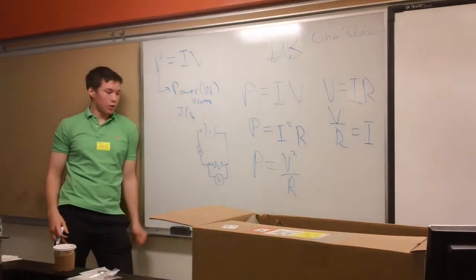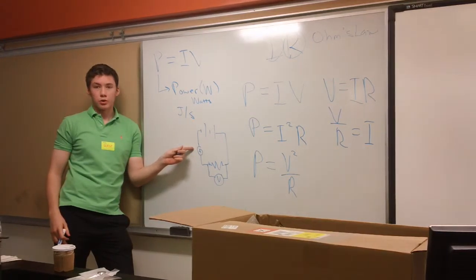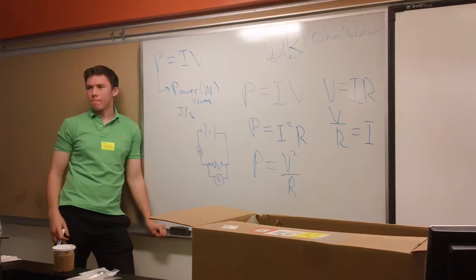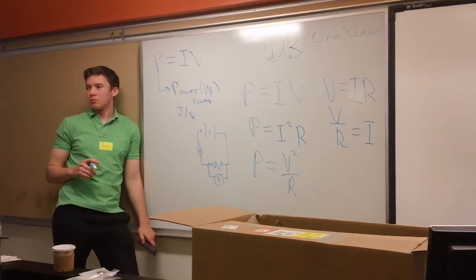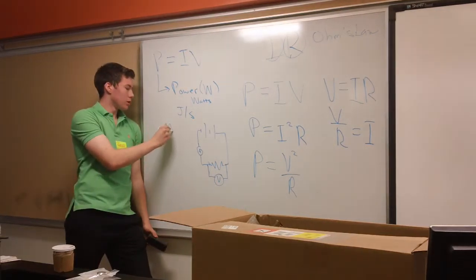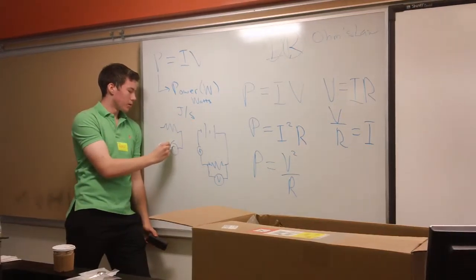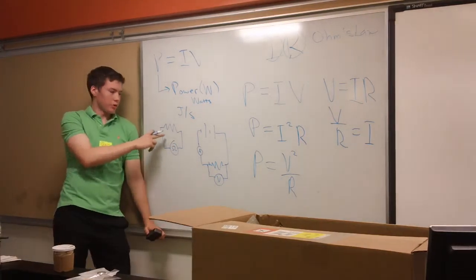And if you're measuring the current, you put the digital multimeter in this configuration, which is known as series. Can I also use the multimeter to find the resistance? Yeah. How do I do that? You just put it across the resistor in the circuit. Yes, that's good, and just take my ohm meter. But not while it's broken, right? Yeah, generally we want to do it like this.